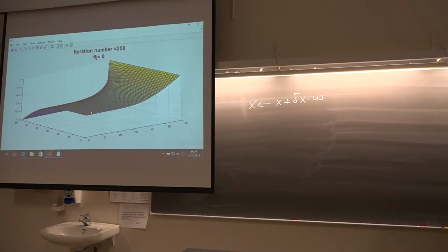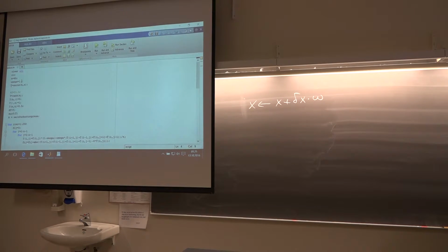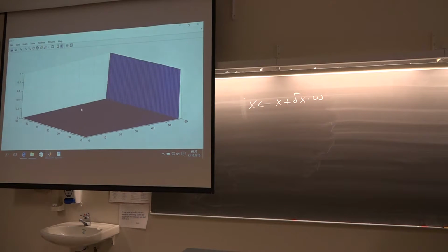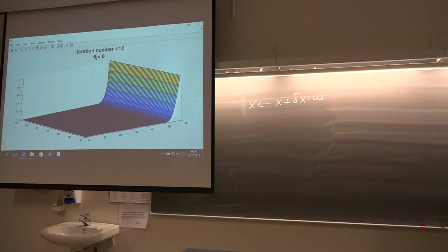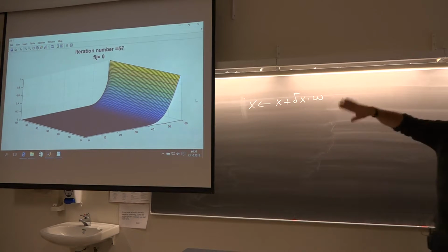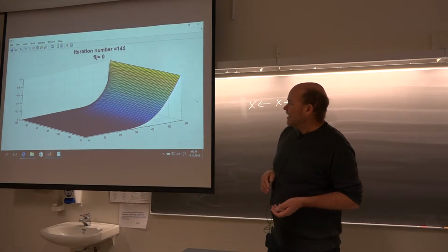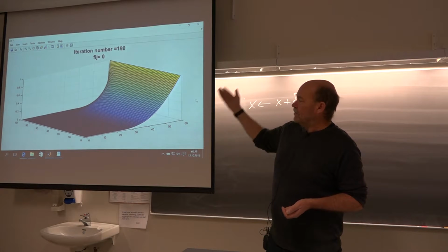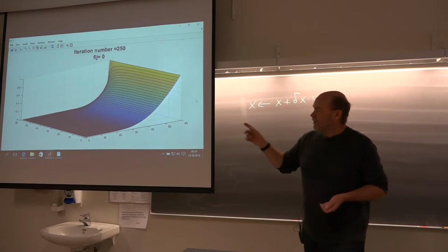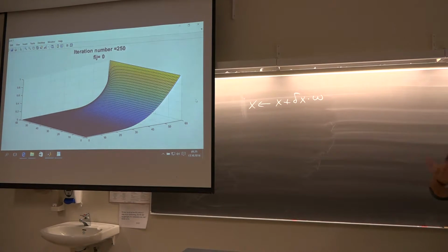I mean, it looks okay, but it's not a good solution. I can show you, if we use the initial 0 solution, it's fast when you have sharp gradients, but when you have a smooth solution, it takes forever to adjust it. So the classical Gauss-Seidel, or Jacobi for that matter, are terrible with low frequency noise, as we call it.